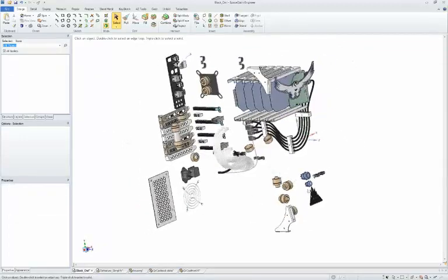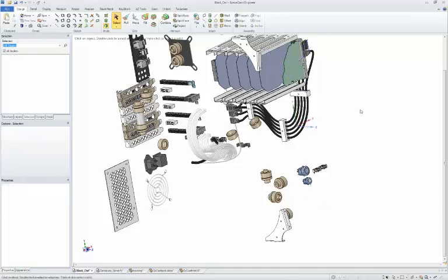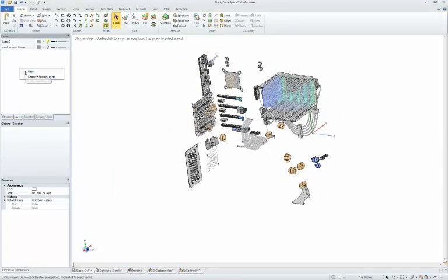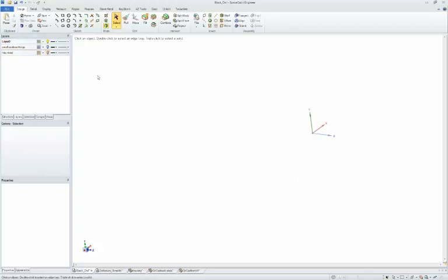I mean, things that are purely cosmetic, I can probably select and eliminate. Just go ahead and delete these bodies. But everything else, yeah, sure, I'll put them on a layer. Put them on a layer and store them there. Put them on a layer called maybe useful, may need. But that's what it lets you do. It lets you prep models, prep assemblies, get things ready for analysis the way you want to.